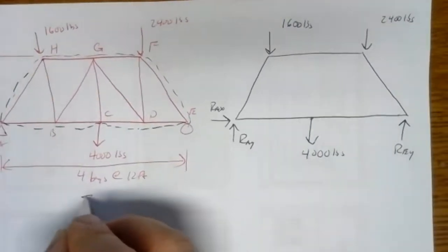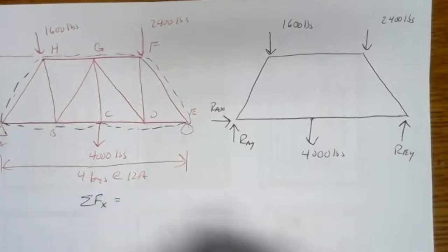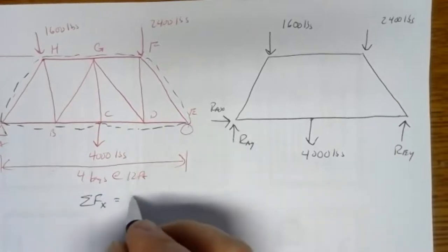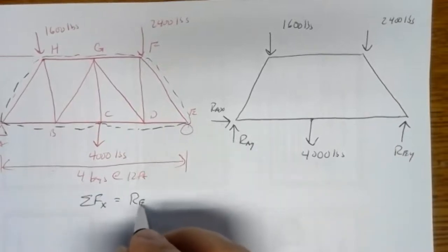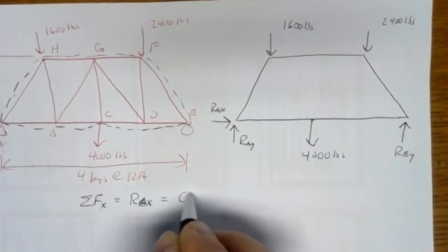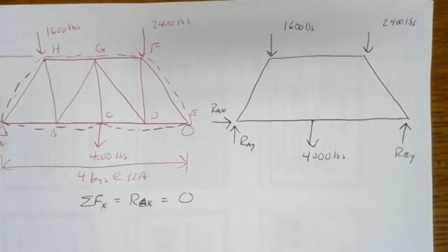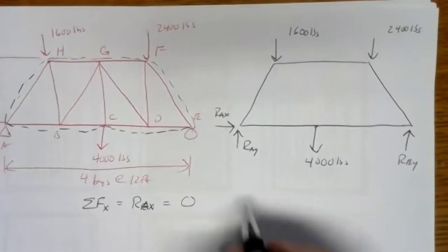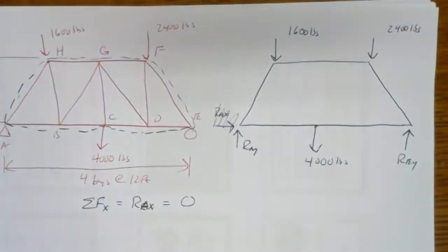Sum of forces in the x direction. All we've got is RAX, excuse me. And since there are no other side loads in there, RAX must be 0. So no RAX.